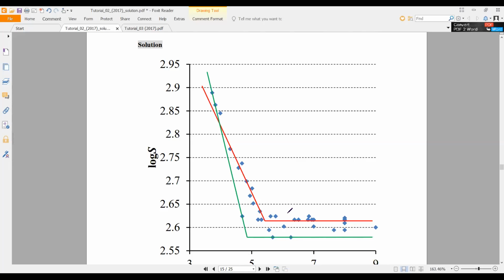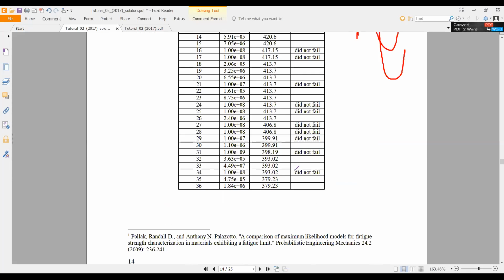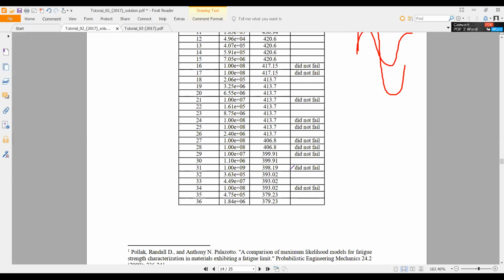Can you repeat your question, because I got some wrong idea of what you asked. There are a set of specimens which did not fail, right? And there's a maximum and there's a minimum. Now, if we take the minimum at the SN curve as SN infinity, where the number of cycles equals infinity, wouldn't that be better? Because that would mean that every specimen there would reach infinity, and that would be the certainty. So that's the meaning of lower boundary.